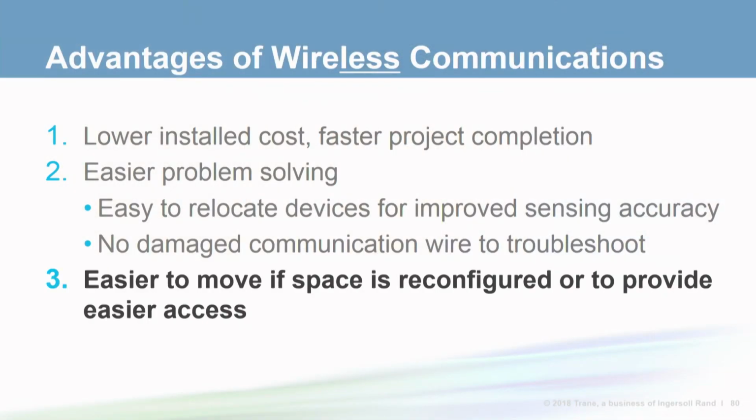Another advantage is that wireless devices are easy to move over the life of the building as spaces are reconfigured, or sometimes when we want to move devices for convenience reasons. Perhaps a user interface is not located where it can be easily accessed. And technicians are more productive and less likely to disturb building occupants if they're free to access the building controls using wireless service tools.